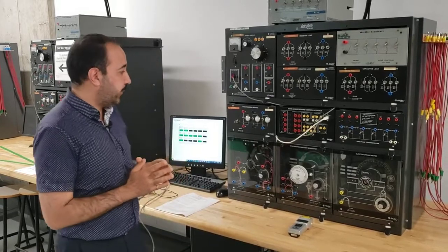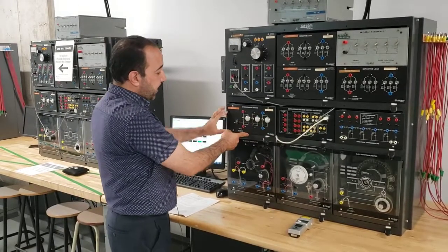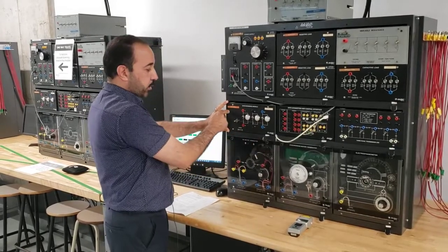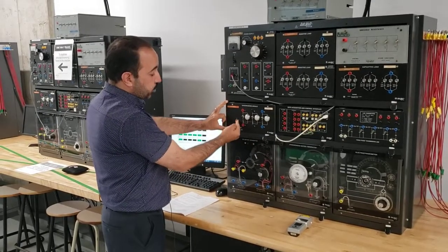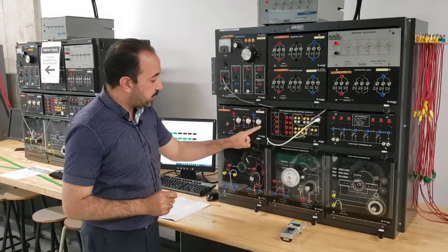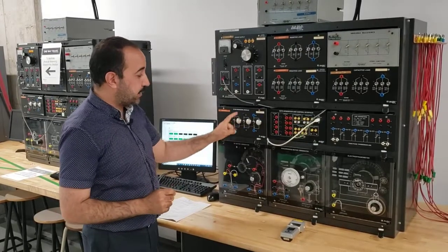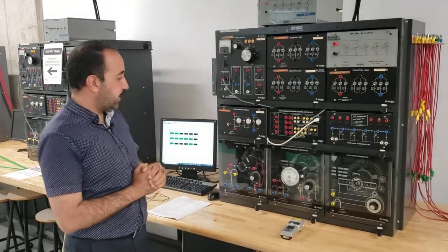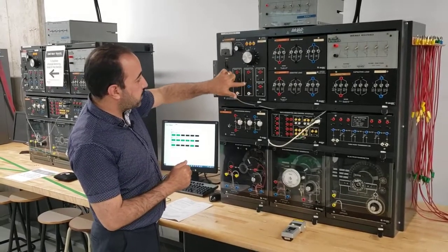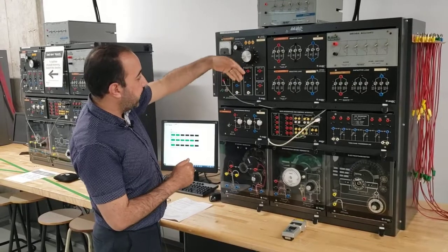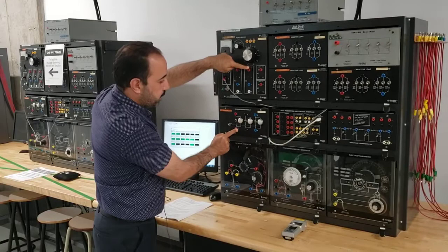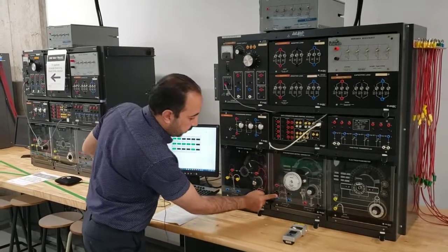What I need for today's lab is the synchronizing module. This module helps me connect the synchronous generator in synchronism with the grid by changing the position of this switch from on to off. Once I see all of these lamps extinguished, at that time I will connect the synchronous generator to the grid. So these three different slots are the power supply that I will use as my grid. These three will be connected to those three, and those will be connected to the synchronous generator.